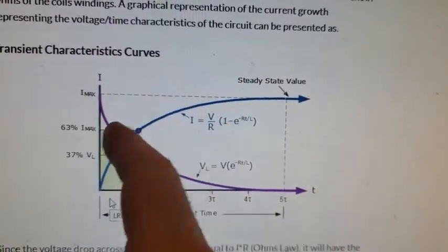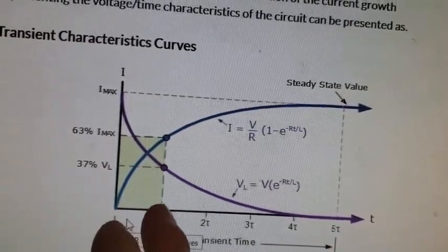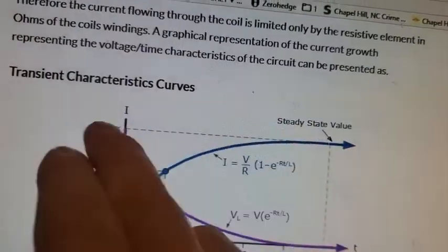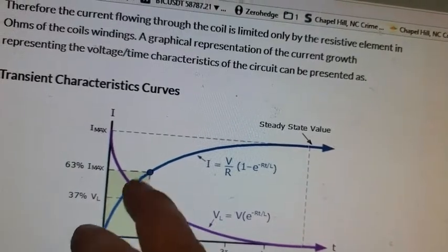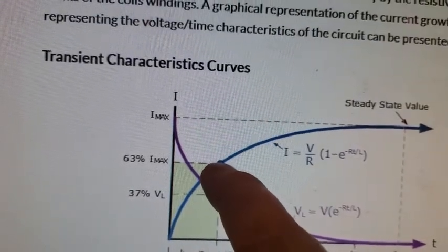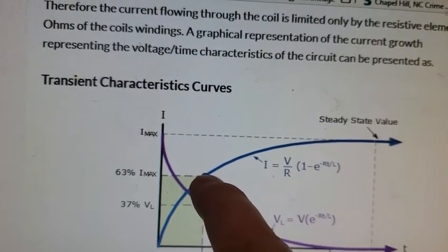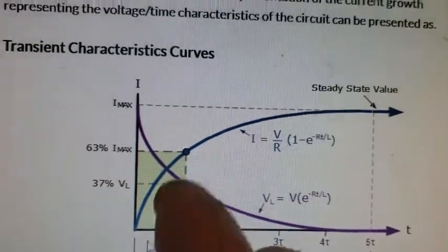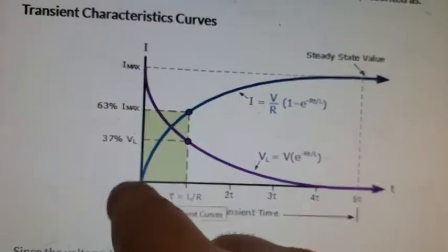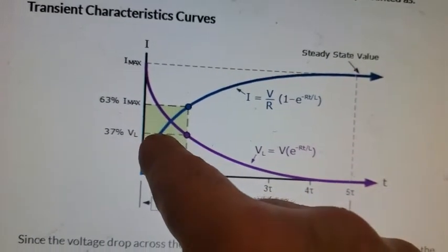And similarly, we can move to the tau time. Now here you're only putting in power for 1/5 as long, and all through here you were close to the maximal amp draw, while here it was far less, and you've achieved 63% of your maximal amp flow, so therefore 63% of your maximal B field magnetic strength, and you've used far less than 1/5. It's like 1/10 or less of the watts in order to establish that. And then the question is, does that continue?